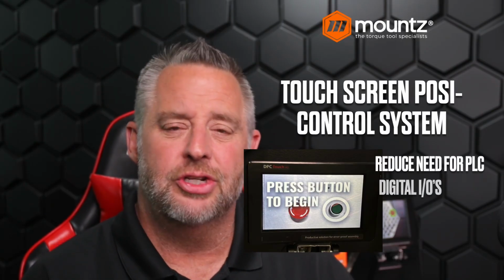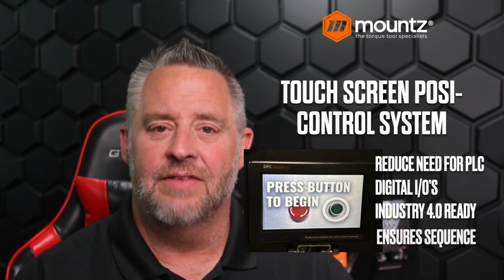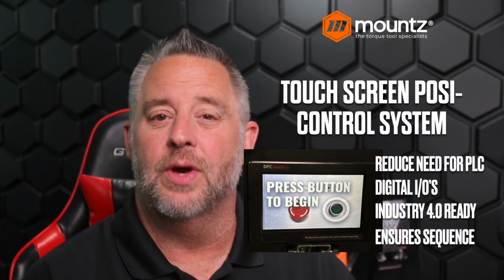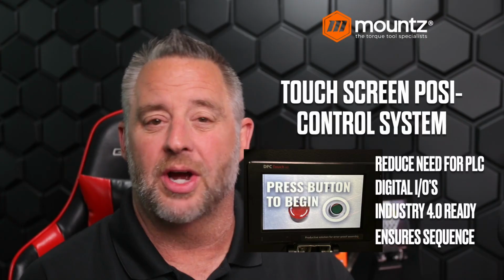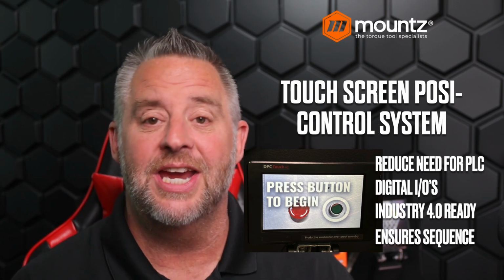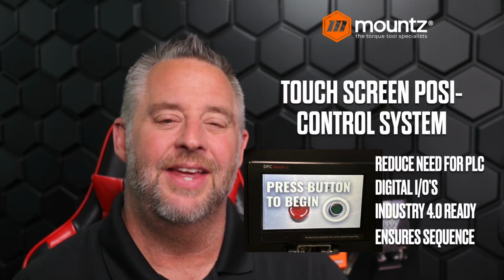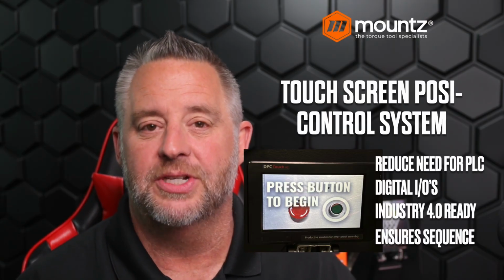Now the Posi system also comes with a controller, which acts almost like a cell PLC. It has 12 digital assignable inputs and outputs that allow you to communicate with other devices. Could be light trees, buttons or switches, or proximity sensors. It could also communicate with a PLC and any other line control devices. They're Industry 4.0 ready, and they ensure proper sequencing of a particular program.